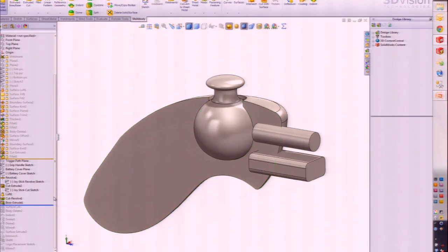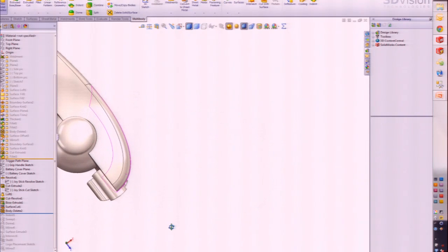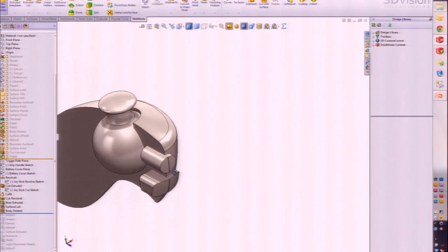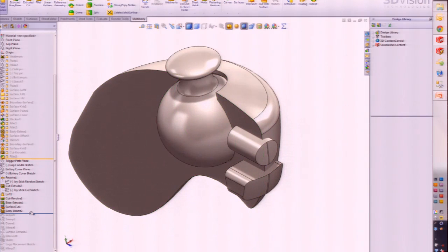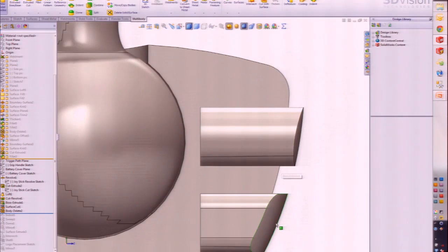Add a couple of buttons, just simple extrusion features. But what this allows me to do is offset from that curved surface to make sure that it follows the exact same contour as the surrounding geometry. All right, more in context. This stuff is really hard to do inside of an assembly, referencing between that part file and managing those external references. The indent feature. So right now what we have are these bodies intersecting the main handle body, right?